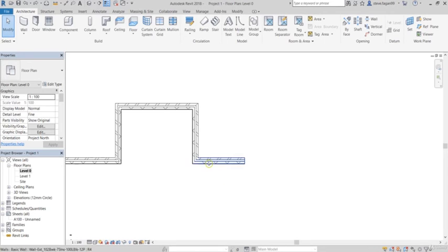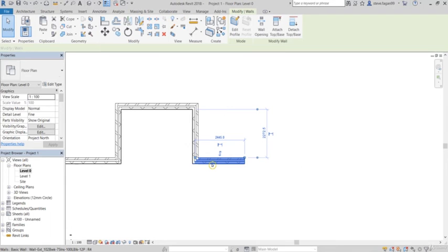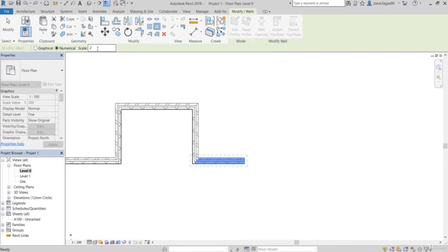So next is the scale factor by numerical. Again, I'll select the wall I want to scale, selecting the scale tool, toggle over to numerical. To scale numerically, first you've got to enter in your scale. So we'll leave it at 2. And then we've got to specify the origin of the scale, the start point.